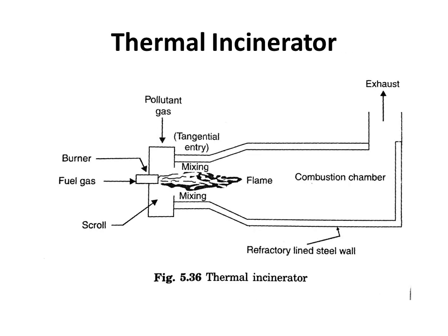Thermal incineration is the most efficient as well as the most flexible technique used for destroying diluted gas streams. In a thermal incinerator, the waste gas is preheated, often over an auxiliary fuel-fired burner, and is passed into a combustion chamber where a temperature of 500 to 800 degrees Celsius is maintained.